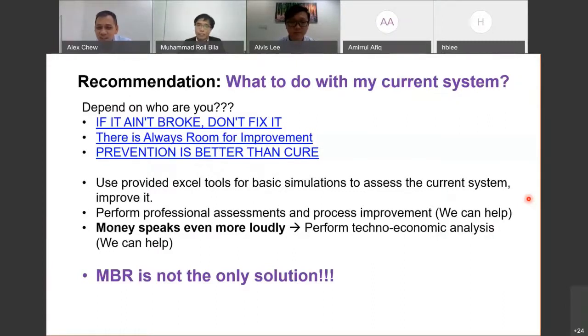It really depends. If you have activated sludge and now you want to upgrade it to MBR, it's very simple. We need to calculate the cost of the membrane, the installation cost, and so on. Then the income will be from the cost saving in excess sludge handling and from the price of water if you use the effluent for reuse. So it will be case by case, especially when you treat industrial wastewater. If you are interested in finding out, just email Mr. Chu, and we'll be able to help you with that. Okay.